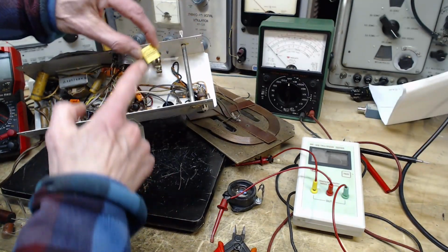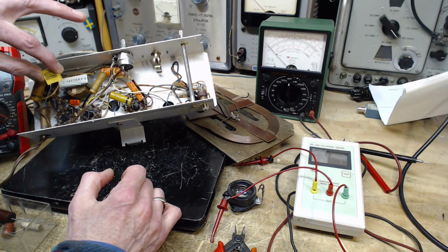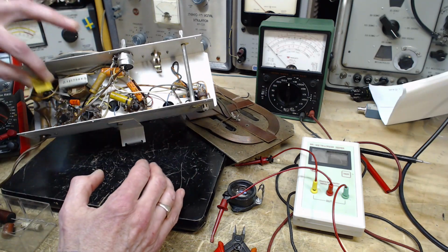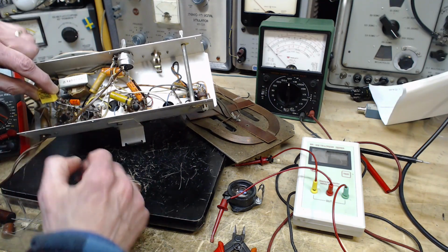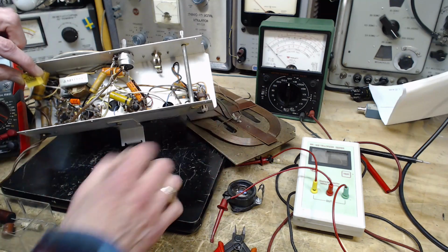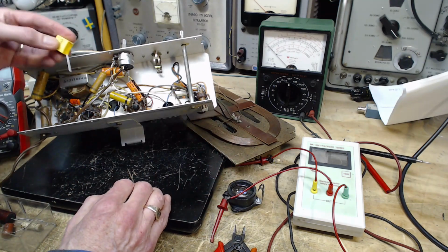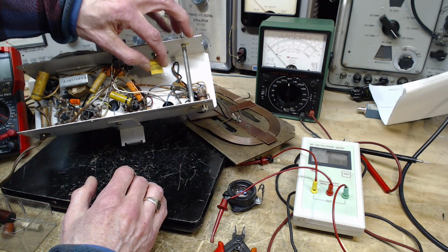In other radios, a capacitor like this goes right across the power line. In some, I had one in here just the other day, capacitor in that position, right across the power line, ahead of the switch. So it was always on the power. Power was always on to it anytime the radio was plugged in. Ooh, that's bad. I don't like that. That thing can give out in the middle of the night.